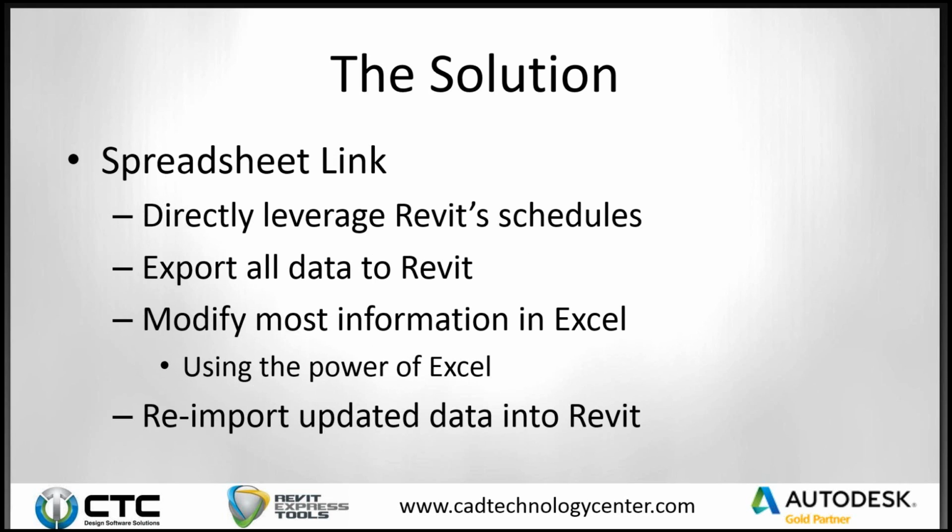The nice thing about Spreadsheet Link, which we're going to work with today, is it can directly leverage your Revit schedules. So whatever you have in your Revit schedule, you can directly push out to Excel and let them use. It can be more of an automated export if you want it to be, so it makes it really quick and easy. You can export all the data from Revit out. Then after you've modified that information in Excel, using the power of Excel and some of its autofill workflows, you can re-import that information back into Revit.